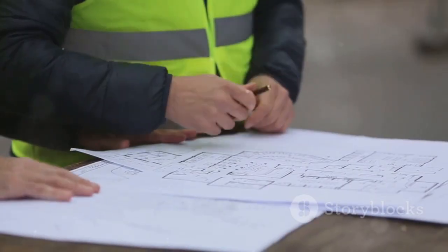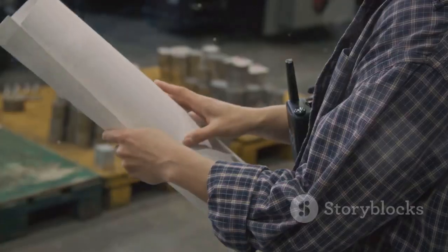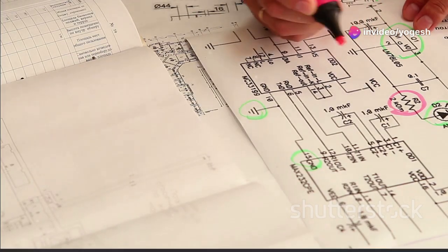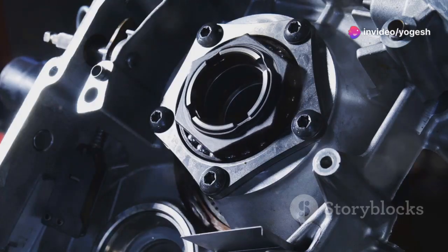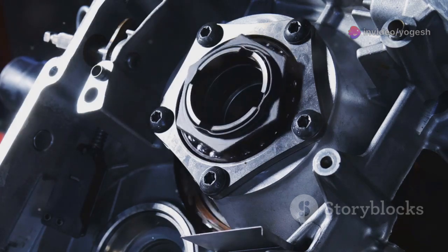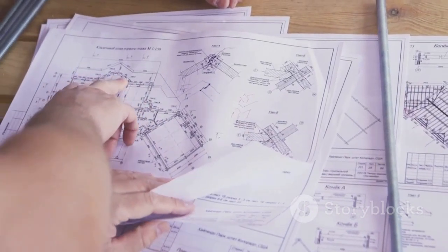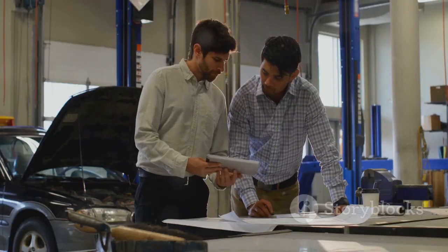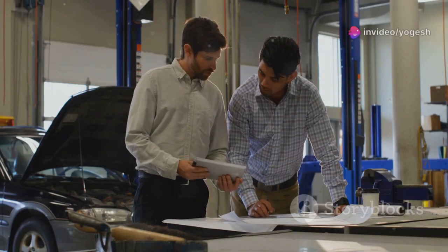Before sending a drawing out, run a mental checklist. Is the section necessary for clarity? Choose the best section type for the part. Check the cutting plane line and labels. Inspect hatching for consistency and clarity. Review dimensioning for clarity and placement. Use center lines effectively. This isn't just about rules, it's about empathy.